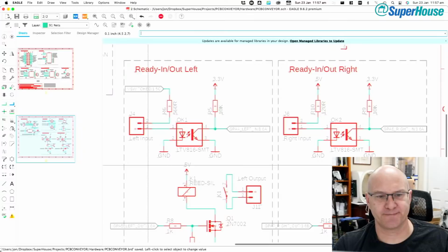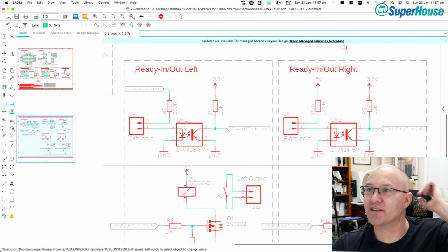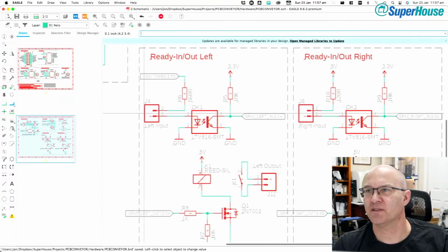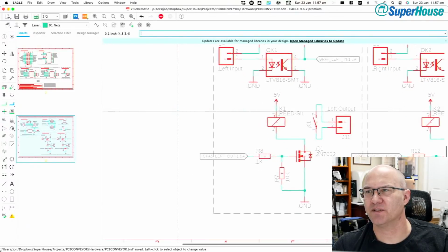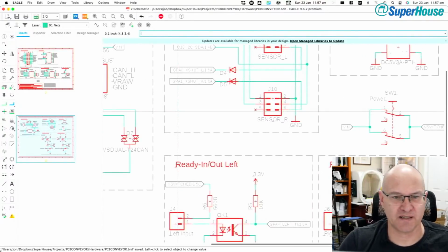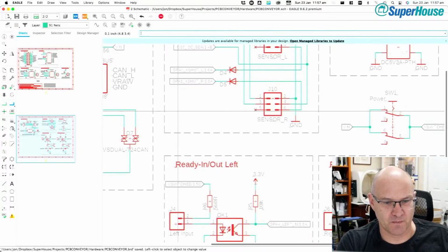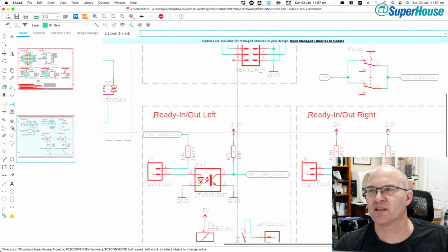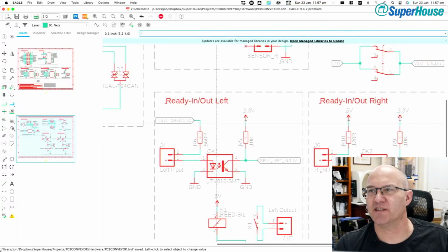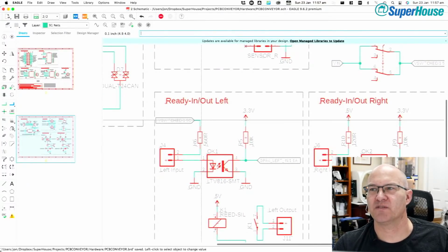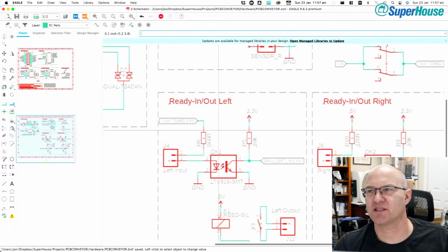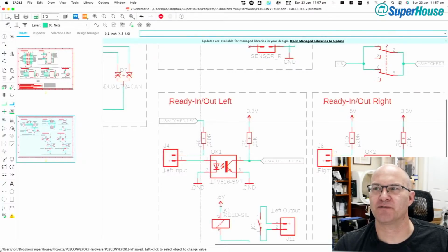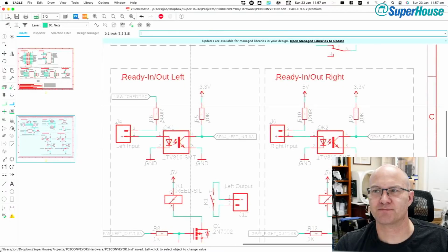So yes. Thanks, Jordan and Johnny. I think that is probably an improvement. It really helps isolate the 5 volt rail from any nastiness that's happening external. Add a diode before the resistor to prevent backfeeding to the 5 volts. Yeah, I see what you're saying. So put a diode in here. That would have a bit of extra voltage drop. Yeah, I don't know. I think this is a better solution. Let's just take the supply for the Opto-isolator off the input voltage, and that should be fine.